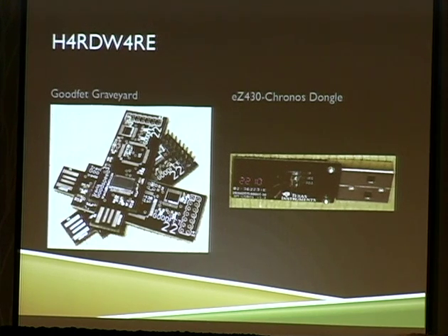Yes, but actually, the first thing that I really messed up was Atlas's dongle for his Chronos watch. As you can see, the only way to flash firmware on this thing is the debugging ports on the back end of it, and you see the picture of it. I learned the hard way that you shouldn't use lead-free solder, because it's bad, and so now I use leaded solder. But basically this broke off. The one header broke off, and if you look really closely, you can see that the pads are lifting off of this. So basically, I completely hosed it. It's the only way that he can flash his watch.